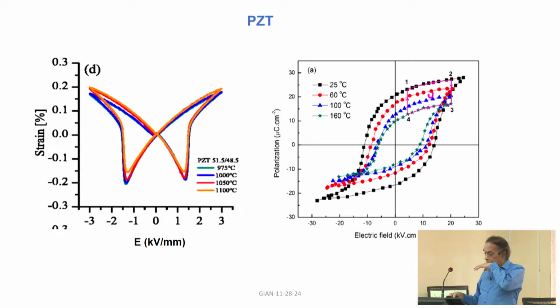So, when you make PZT, you have to be extremely careful, because lead has a tendency to evaporate and escape from PZT. So, in order to avoid any loss of lead that you need in the PZT, you always disperse some lead around it. That will compensate for any loss, and then you can get stoichiometric PZT.